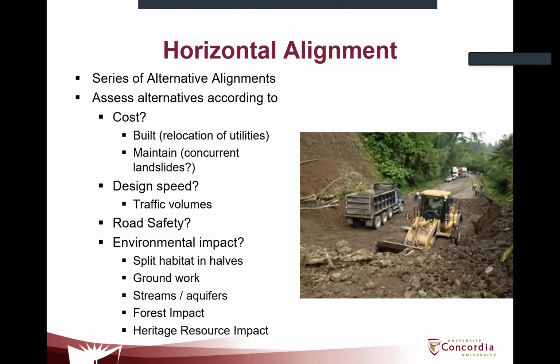So the horizontal alignment, you will look into all those aspects as we have discussed and assess the alternatives based on the cost that it takes in the initial construction, the relocation of utilities, but also the cost of maintenance. So you could spend not much money and make very steep cuts in the terrain. But if this is going to make you incur in maintenance and closures of the road because of landslides, then the design is not good.